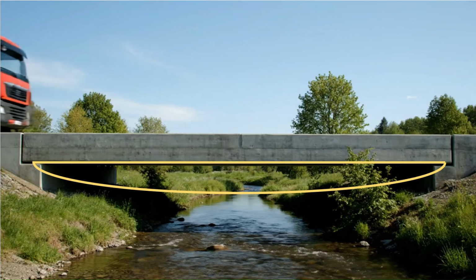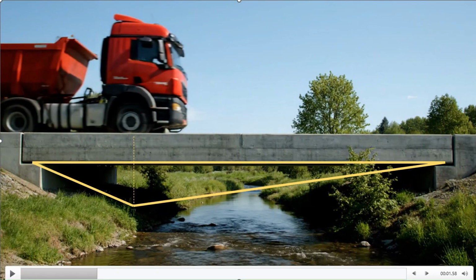Now let's have a look at the combined effect of both a uniform distributed load and a point load. For the UDL on a simply supported bridge, we know that the maximum moment occurs at midspan. We also know that for a single point load on a simply supported span, the maximum moment occurs where the point load is applied. However, when we combine a UDL and a point load, it's less obvious where that maximum moment is. In the example that follows, the maximum moment occurs at neither position, so I'll show you how to work out where the maximum moment occurs and then how to calculate that moment.